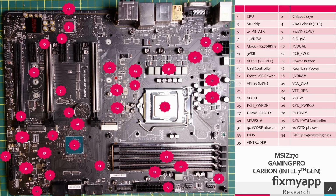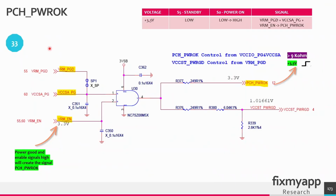PCH power OK signals are created in this region. In power sequence 33 we need to create a PCH power OK signal. PCH power OK is a status signal that informs the PCH, the platform controller hub, that the power to the system is stable and in acceptable ranges. It is generated by the multi-phase PWM controller that generates core voltage of 1 volt for the CPU. If that controller is operating correctly and the VCORE voltage is generated, it will send a VRM enable signal, a power good signal, and also the additional CPU voltages will send a power good signal to this chip.